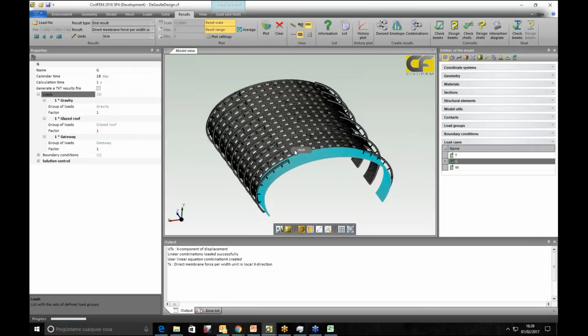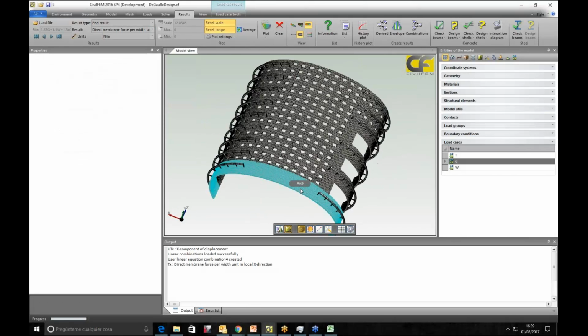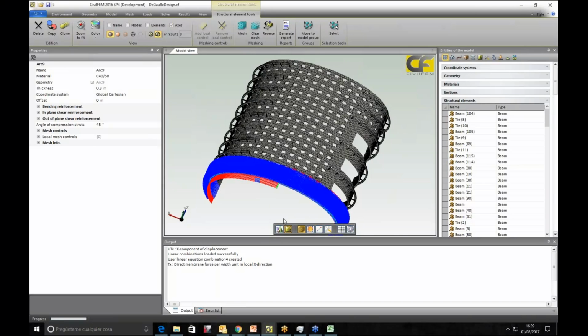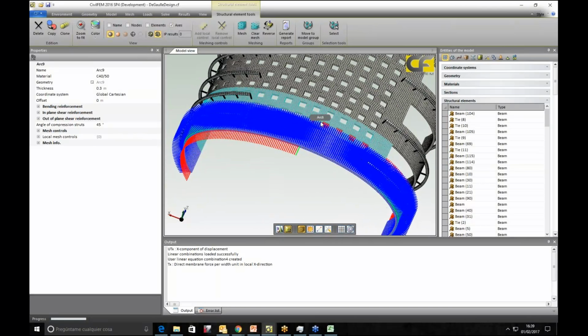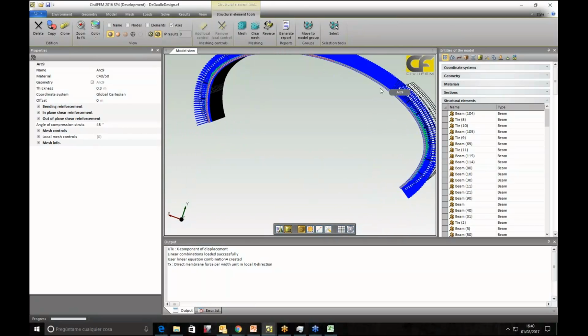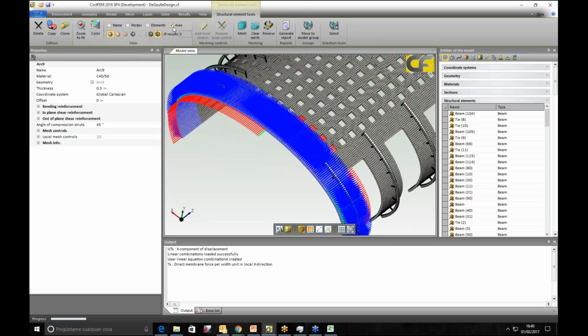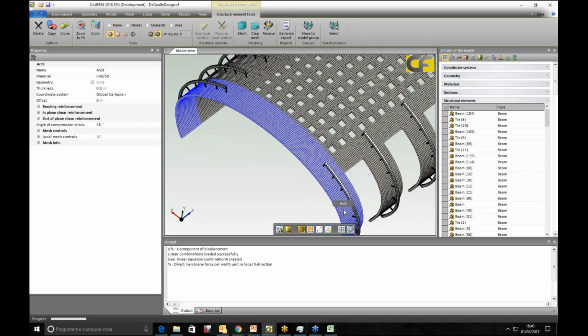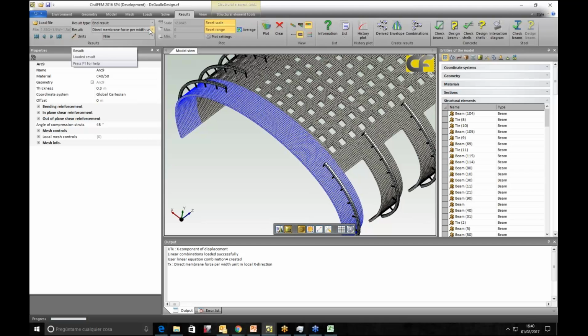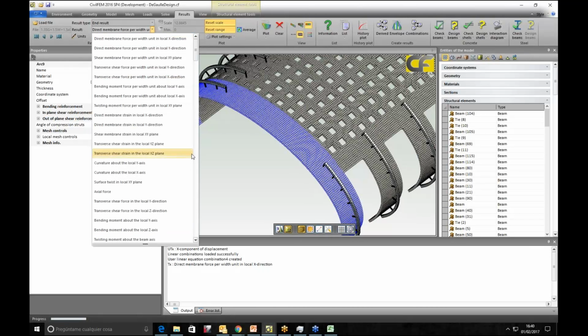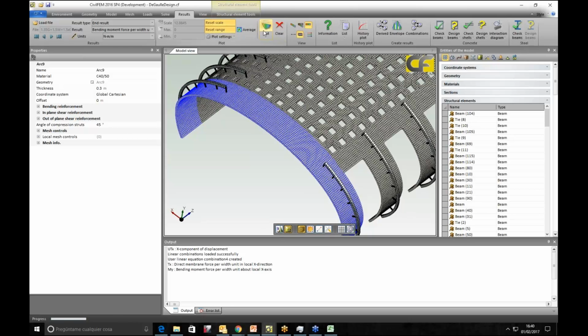Here for the bending moments and also reinforcement amount directions, if I plot the axes of the model, we can see that the horizontal axis is X and the circumferential axis is Y. So, taking that into account, in Y direction and X direction will be the bending moments and reinforcement. So, plotting results, as an example, bending moment per unit of length in X direction, in X axis.